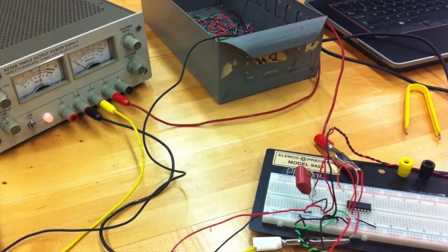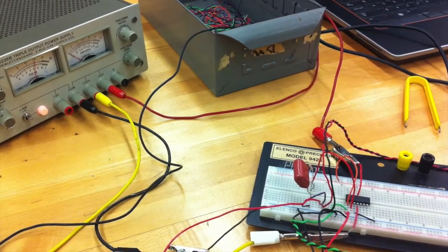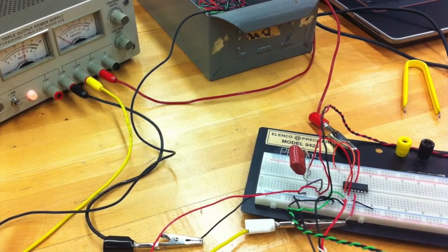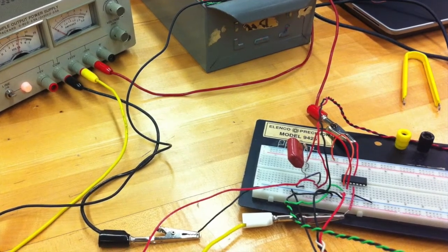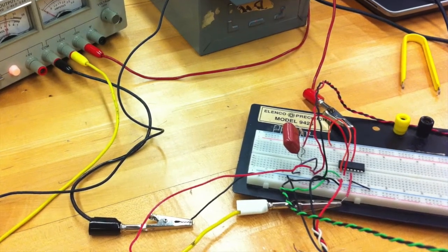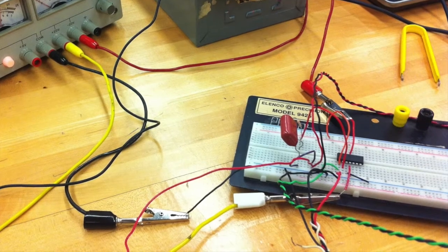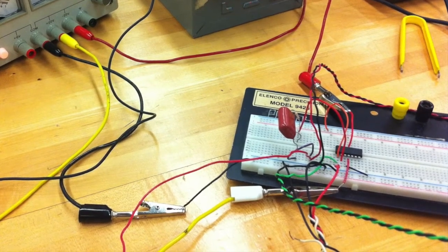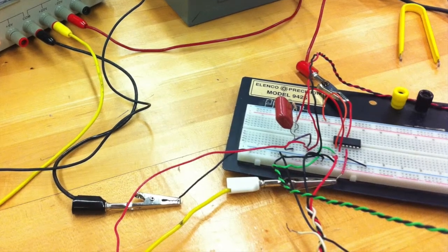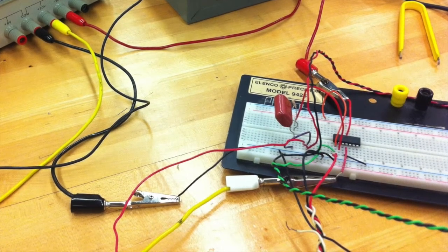15 volt power supply. To choose the value of our resistor, we first decided on a frequency of 600 Hz, because that's where we wanted the cutoff for amplifying and blocking the frequency. We used the equation frequency equals 1 over 2 pi RC to calculate a resistance of 265 ohms. We used a 270 ohm resistor giving a 589 Hz frequency.